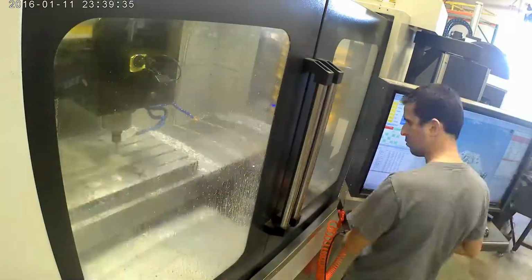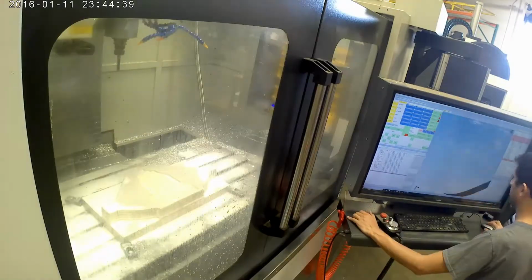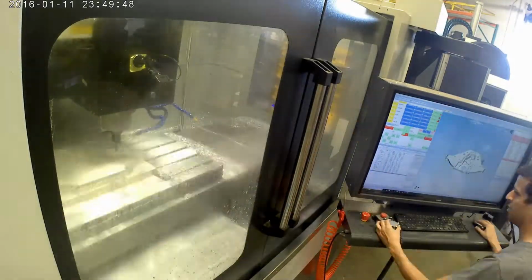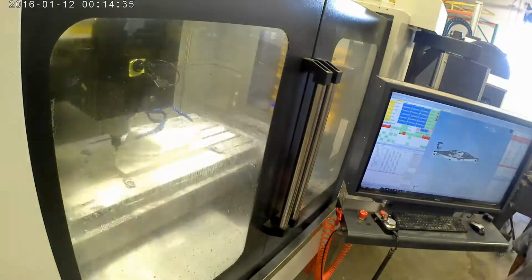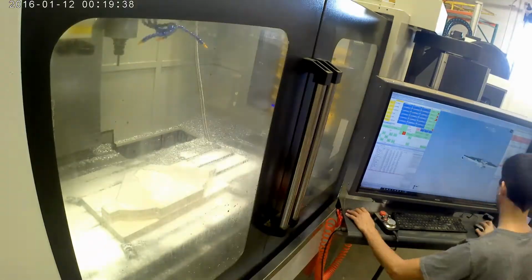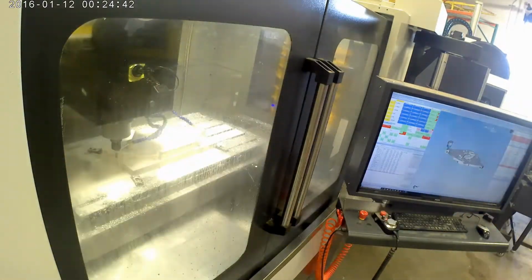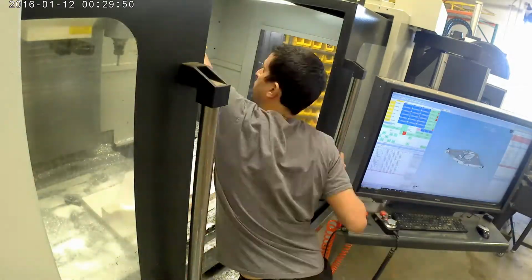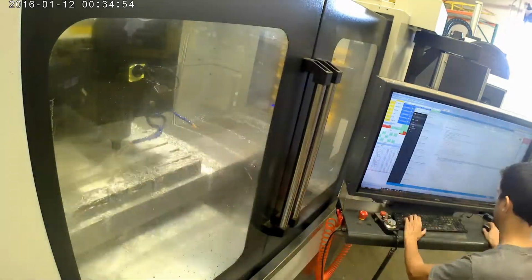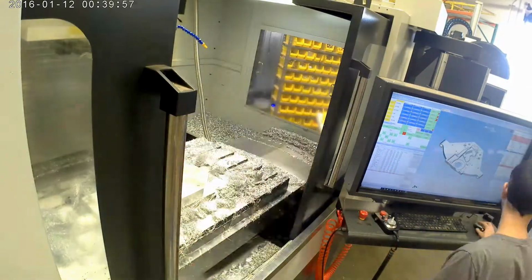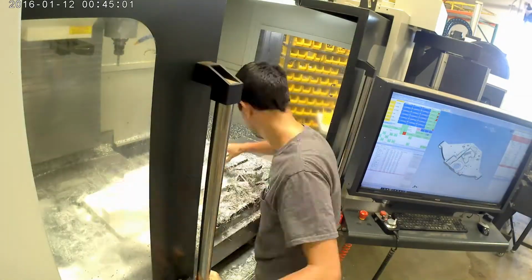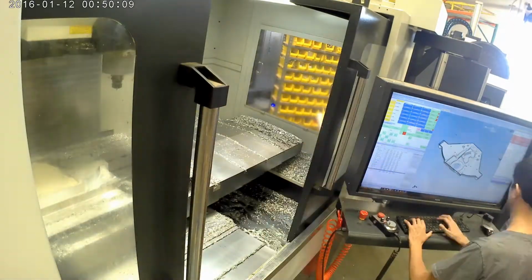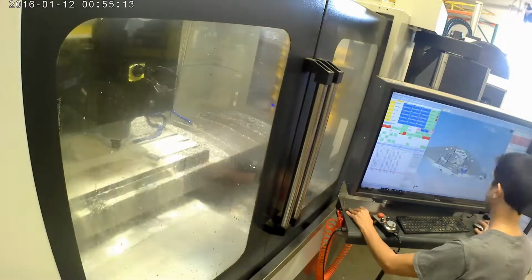So what we can do is just click on the bolt hole in the CAD model and tell the machine to move there, which is something you cannot do with G codes, or at least not as easily. You have to go back to your CAD CAM and get the XY location, and then come back out and move the machine to the XY position. So it's much faster when you have the CAD CAM integrated with the machine. We're going to show that right now.